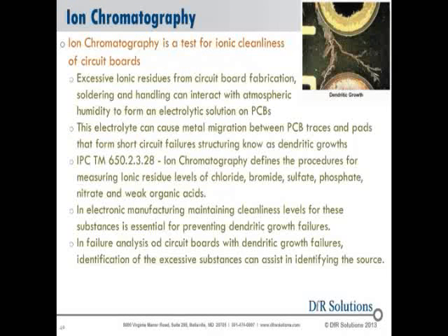A chemical analysis technique known as ion chromatography is an evaluation method for the ionic cleanliness of circuit boards, either raw bare boards or circuit board assemblies. Ionic residues, which come from chlorine, bromide, sulfates, phosphates, nitrates, and weak organic acids that electronic devices are exposed to during the electronic assembly and manufacturing process.